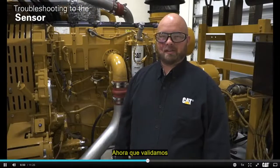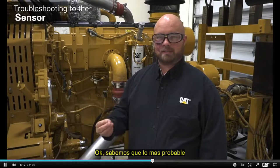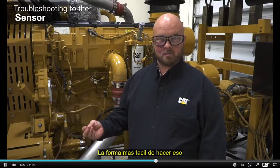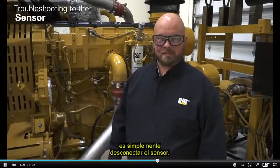Now that we've validated the power going to the sensor, our next step is going to be creating the opposite condition out at the sensor. So what's our code? -4, voltage below normal, okay? We know that that is most likely going to be the result of a short circuit condition. So to create the opposite, what are we going to do? We're going to make an open circuit condition. The easiest way to do that is to just go out and disconnect the sensor.